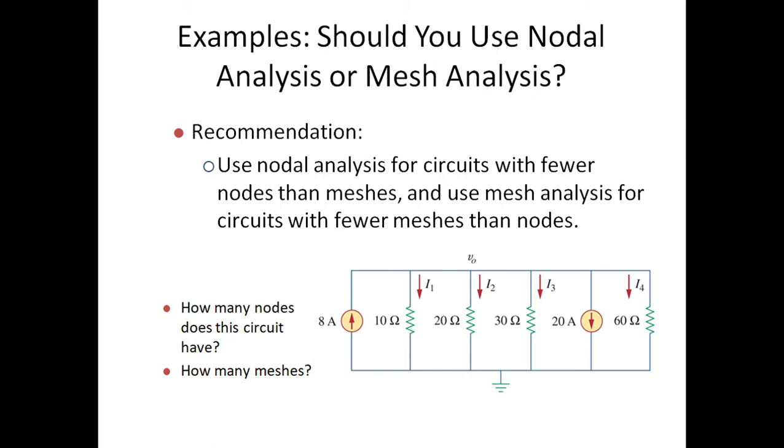When do you recommend nodal analysis or mesh analysis? We use nodal analysis for circuits with fewer nodes than meshes, and we recommend mesh analysis if the number of meshes is lesser than the number of nodes.